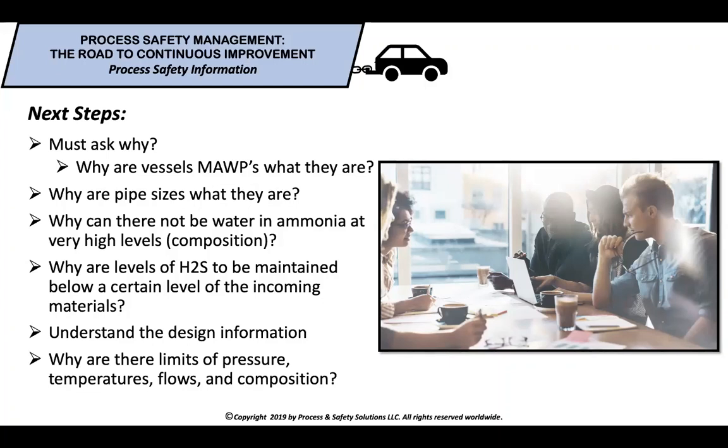So when they went to the 8-inch pipe, the velocity increased significantly, and of course, so did erosion. It eroded the pipe and had a major release of gas, and a fire and explosion occurred. So this would be a safe limit, in terms of flows. We want to limit the flow or the velocity in a pipe. That would be a safe limit that we'd want to make sure we're documenting in our process safety information.